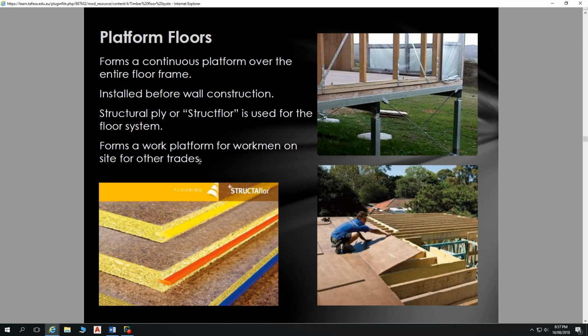So, platform floors. It's where all your floor sheeting goes down, and then your wall framing goes on top of it. So here, this is structural floor. That's very common. One word of warning with products like structural floor: do not use them outside.